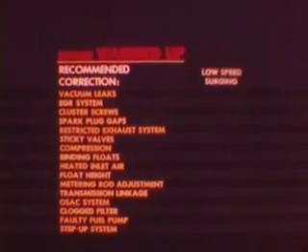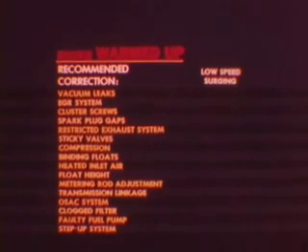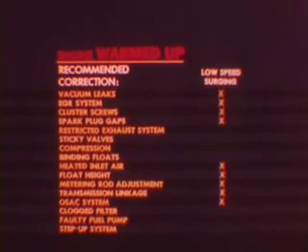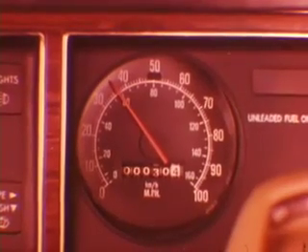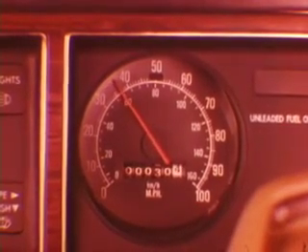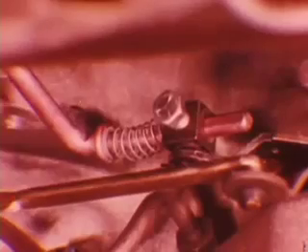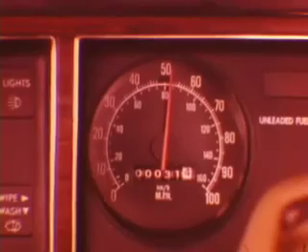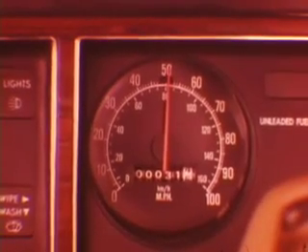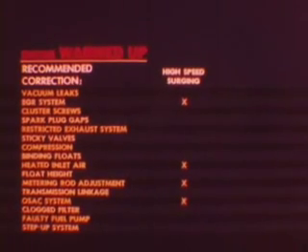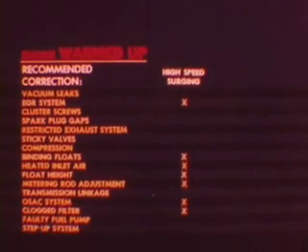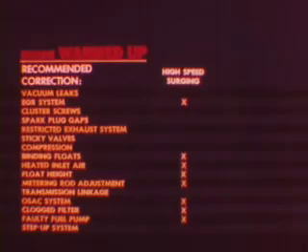Next, we come to surging when cruising below 40. Here again, we are concerned with lean mixture causes, incorrect timing advance, EGR mixture dilution, incorrect spark plug gaps, or fouling. Early and mushy transmission upshifting can be mistaken for an engine surge condition. Transmission throttle linkage, which is adjusted too short, can cause this condition. Engine surging when cruising above 45 may result from any of the low-speed surging causes, plus low carburetor float height or binding float arms, clogged filter, or a defective fuel pump.